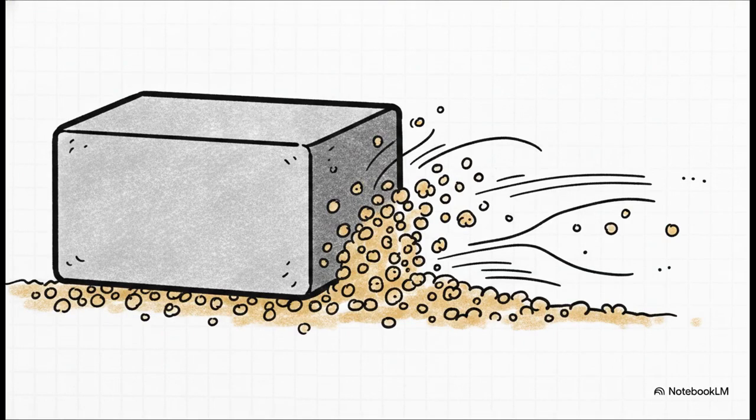The reason for this really drastic reversal comes down to the fundamental nature of sand itself. Sand is cohesionless, it's granular. Near the edge of the loaded area, sand has way less confinement. There is simply less overburden resistance from the sides to actually hold it in place. So when pressure is applied, the sand at the edges simply tries to escape. It deforms and weakens laterally. Therefore, if a rigid foundation wants to stay perfectly flat, it actually has to reduce the pressure at these weaker edges. Otherwise, the edges would just sink away entirely.